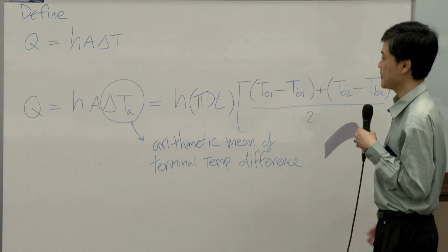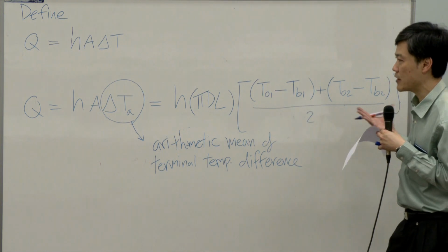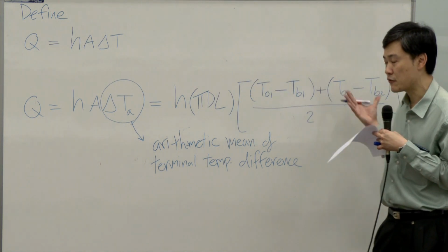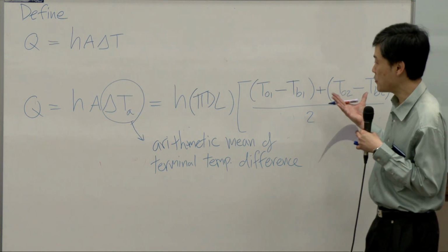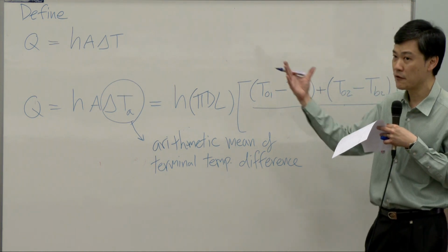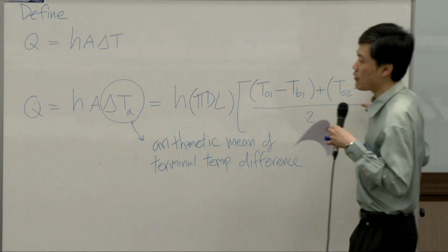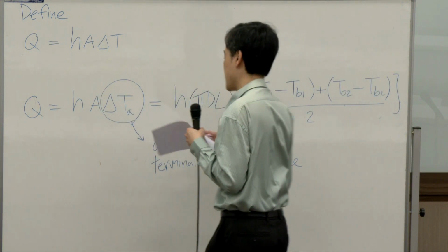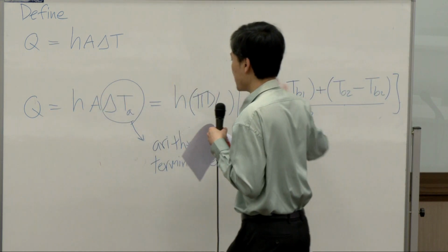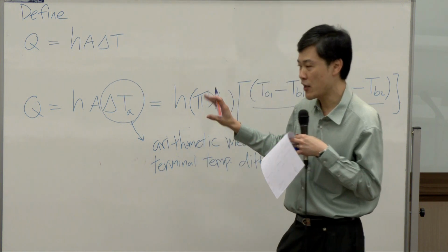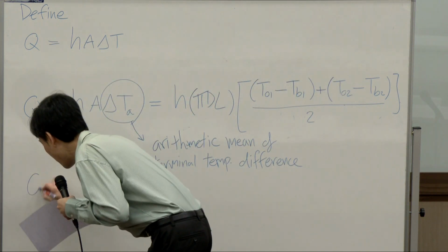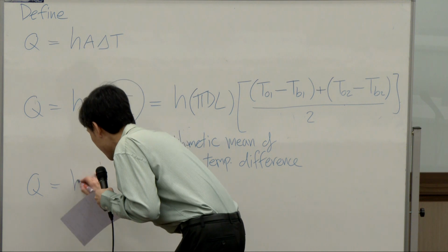Okay? So I still rely on Newton's law of cooling. I still rely on the driving force. But now I used the average driving force throughout the pipe. That's one way to do the calculation. The other way, if you already learned the heat exchanger, you will be more familiar with this equation.